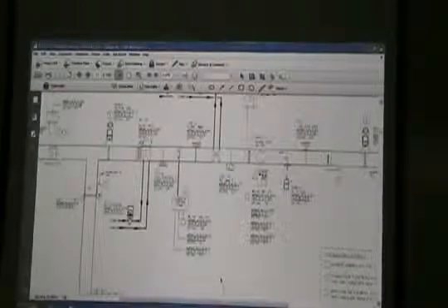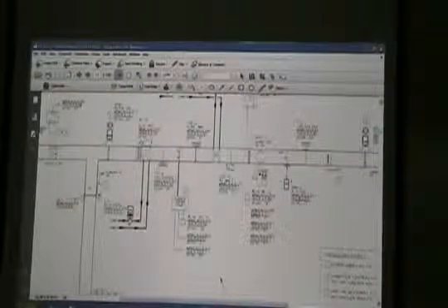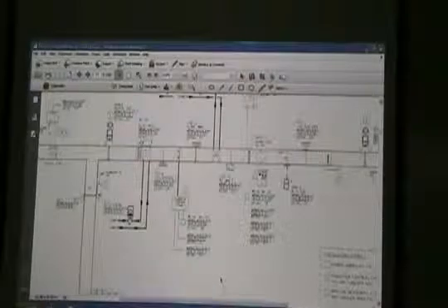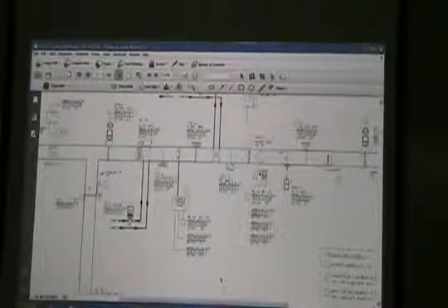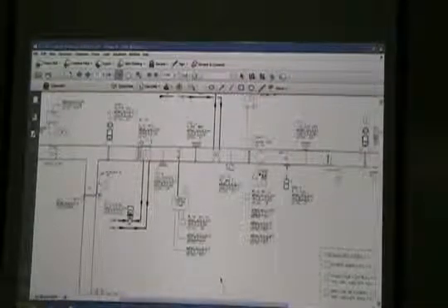So we've got this thing going wide open, so we could be generating 100-degree air, but we want to generate 55-degree air out of the unit, because this is a cooling-only variable volume application, meaning that all the heating is done out at the air handling unit or out at the VAV boxes. So we're still wanting to maintain 55 degrees right here all the time. So even though this valve is wide open, we take these dampers and modulate them around.